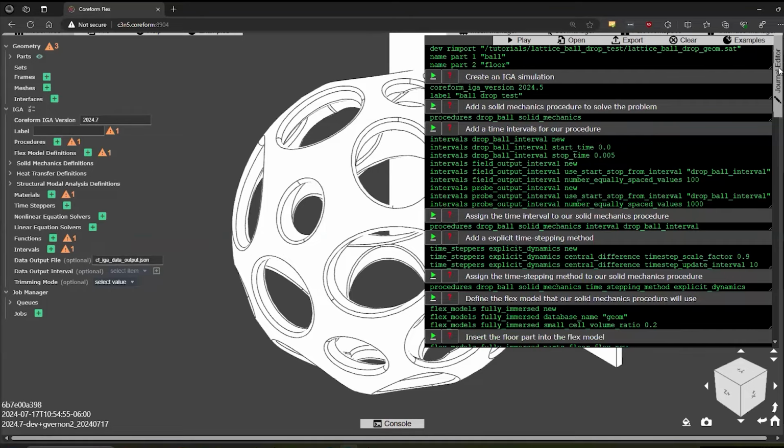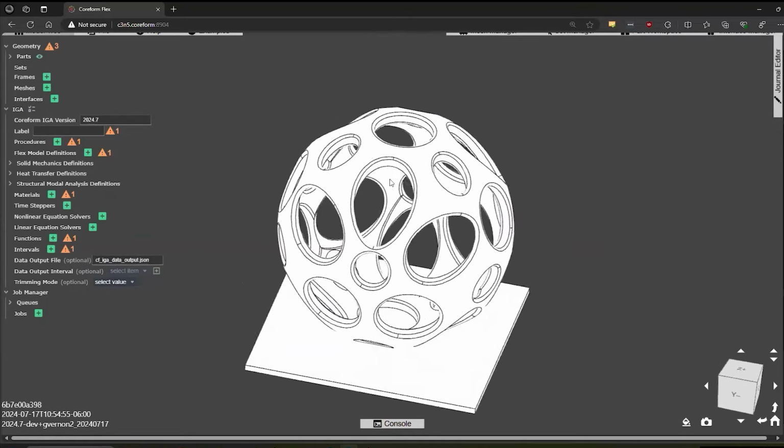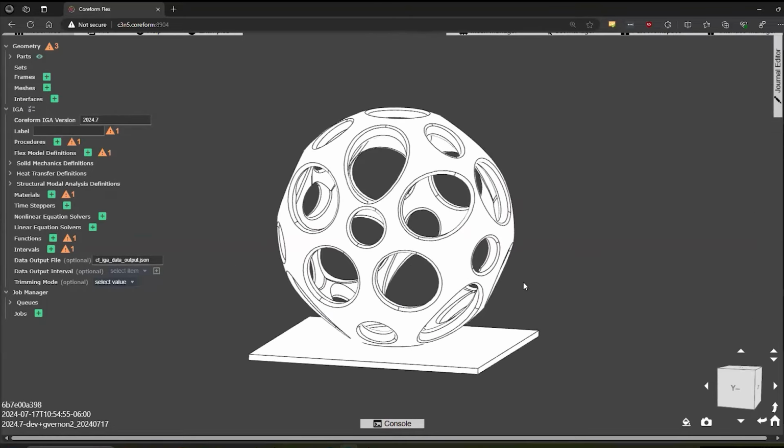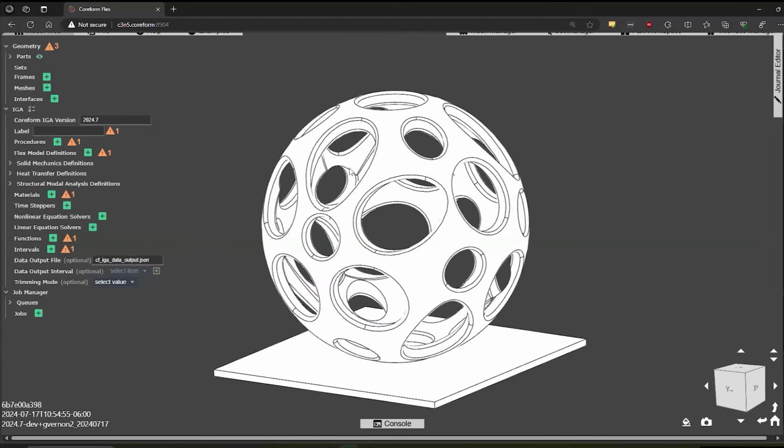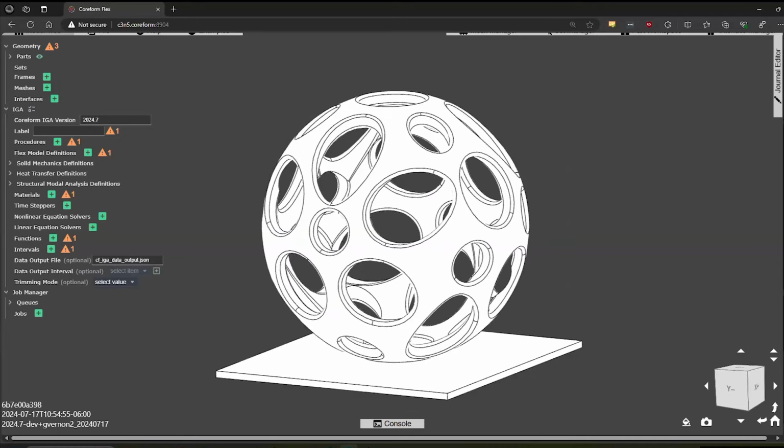And as you can see, again, a fairly complex geometry. If I were going to do this model with traditional approaches, I would remove all of these little fillets, and then I could probably mesh it from the inside outwards with a sweep. But then I've lost those fillets, and so I've kind of changed the problem.